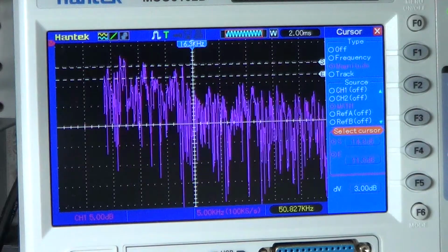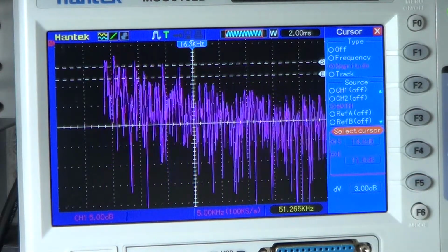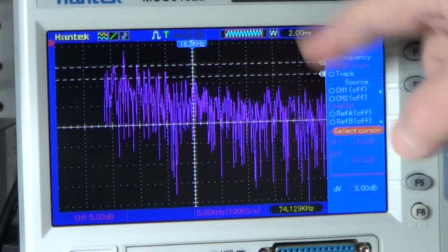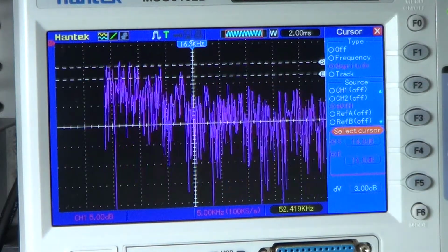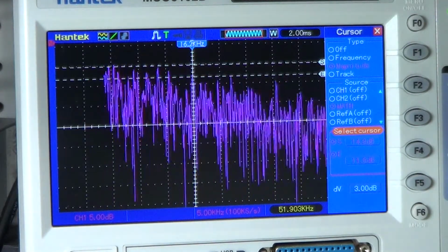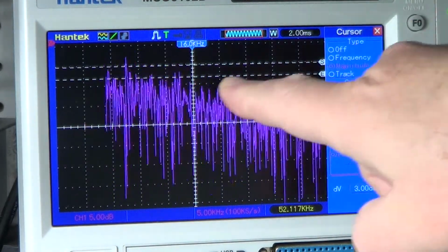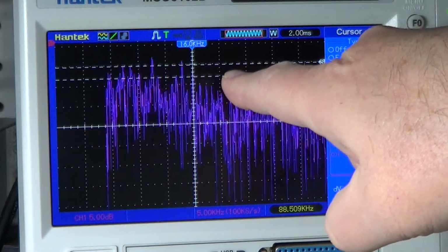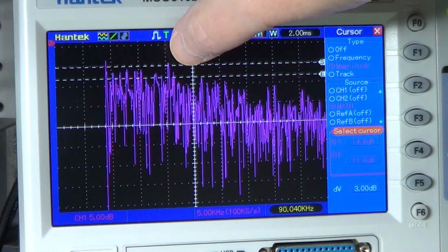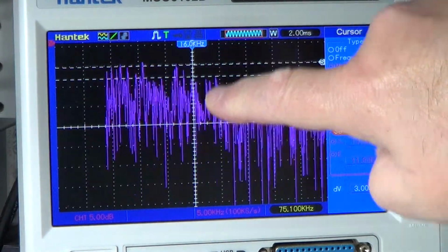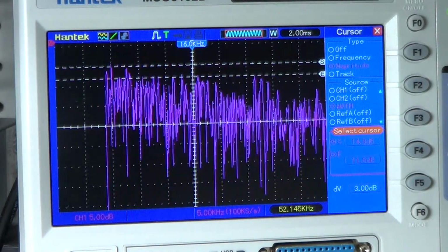Since all the frequencies generated by a noise generator are different frequencies and different amplitudes, it's difficult to do these measurements because the top of this line keeps jumping up and down. So we had to make a rough estimate to do that. And I'm thinking I'm gonna stop over here. Seems pretty good. I mean, here there is almost nothing else, and here there are still things. So this is basically the cutoff frequency, which seems to be 16 kHz for the component I've chosen.